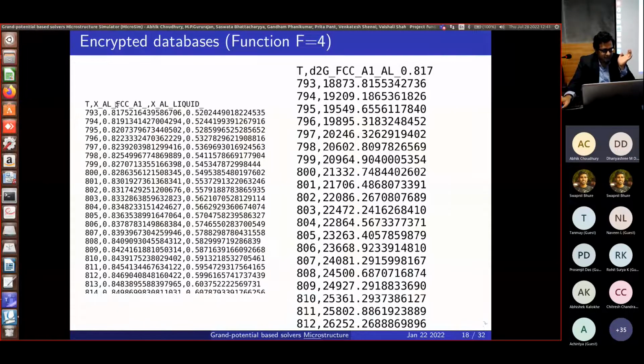For a ternary, you will have corresponding two columns for the solid phase and two columns for the liquid phase. So this is how the composition file needs to be extracted from the TC API or Pan API. Similarly, this is the Hessian matrix, where for the temperatures, you can extract the d²g/dc² directly from the info.